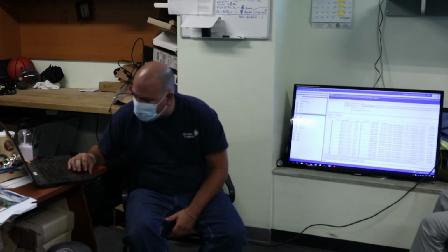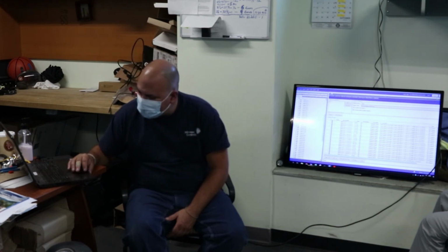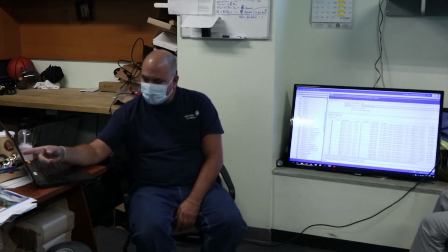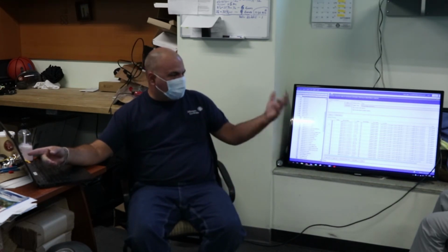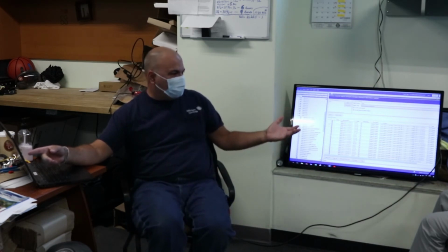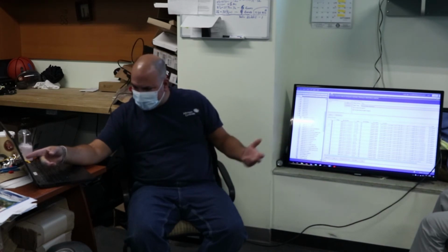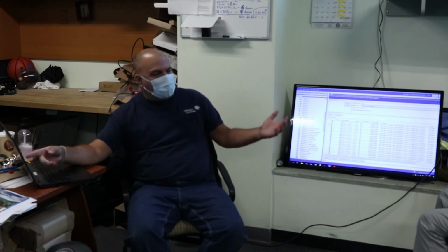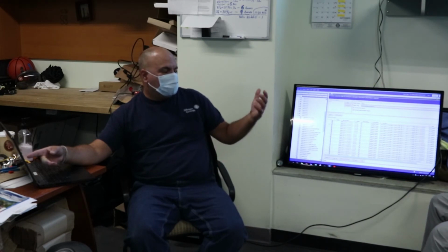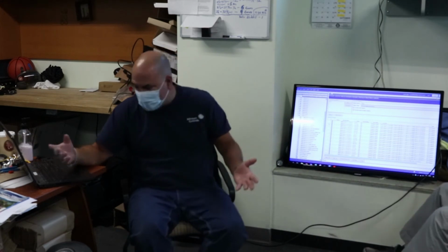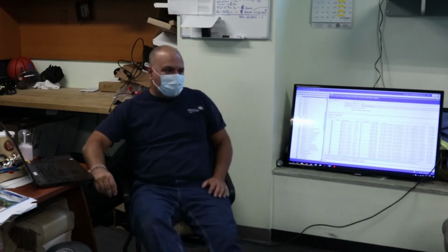So if you're looking for a VAV, right, open one up, and these are the tags you'd be looking for. Supply air temperature you wouldn't need because that's coming from the air handler, so you don't really need to see all the VAV supply air temperatures. The heating valve, though, you can do the heating valves, you can do the zone temperature. The DAVP, that's the velocity pressure, and that basically calculates your CFM. You don't really need to see that. But you can do all your CFMs and everything like that.